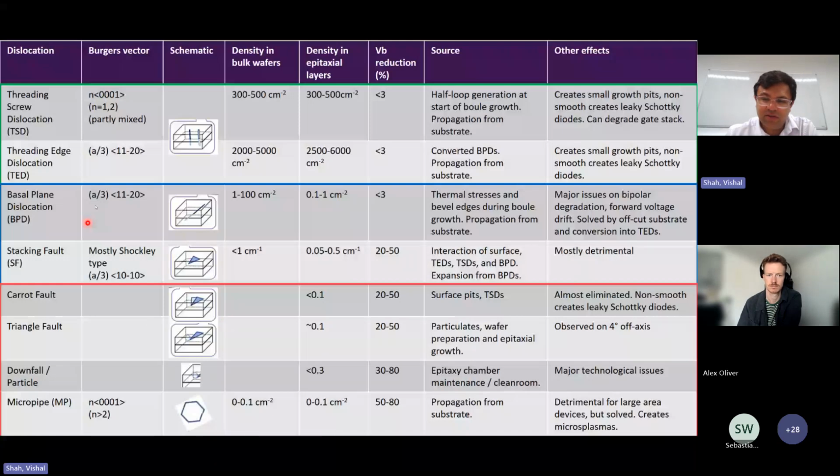There are then these blue ones, the basal plane dislocation, which can turn into the stacking fault, which need to be monitored because they can be a point of failure even if they are not a device killer. And then there's the green ones here, which are unavoidable within the device or the substrate themselves. And they essentially are 1D defects, and they can affect the device performance, which now that silicon carbide is a very high TRL level material and is a production device, there's a lot more interest in trying to detect these defects. But they being one-dimensional can actually cause problems in detection.